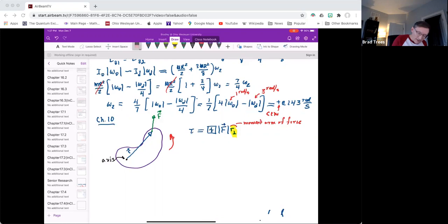All right, so now let me talk about that. How do you find the moment arm? It's basically a two-step process, starting with the picture you've got right here. First, take the force itself, the force vector, the green arrow in my drawing, and extend the line of that force. I draw it with a dashed line, either way, above and below the force. That extension of the line of the force is called the line of action of the force. You have to draw that if you're going to get the moment arm right.